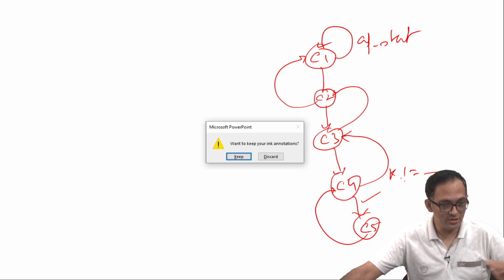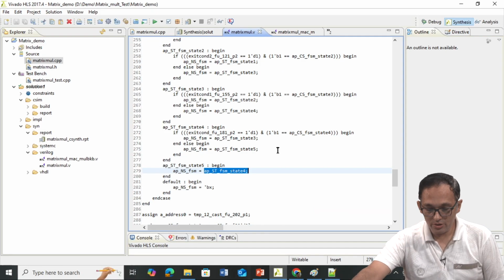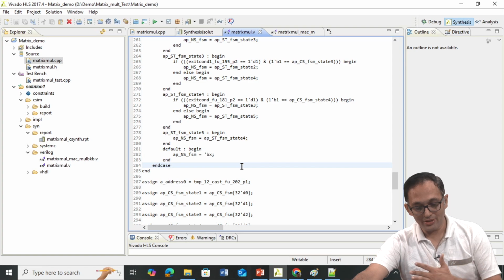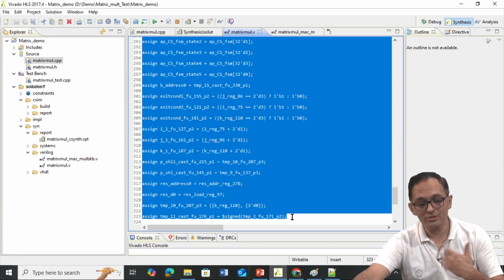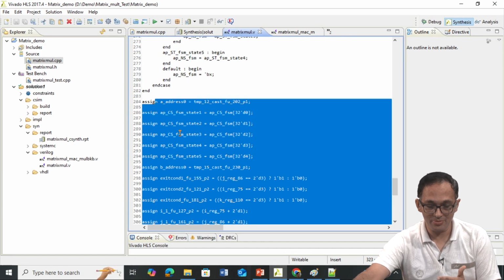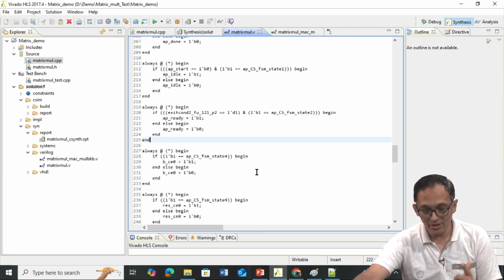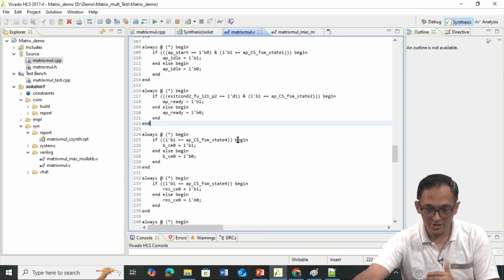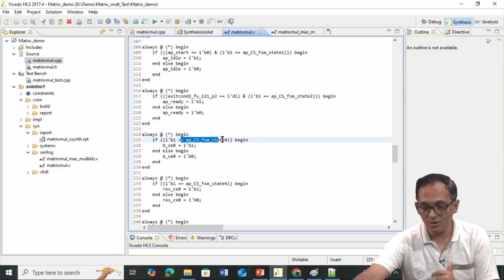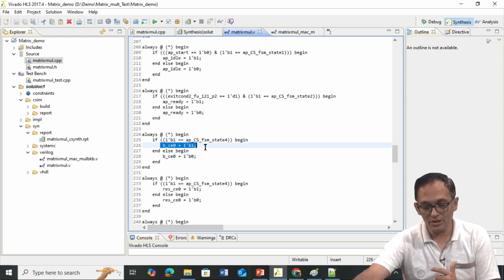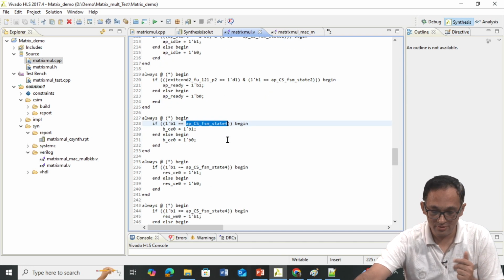Okay. So, we understand exactly what this controller implements in the Verilog. Now, look into the code, what is the data path and all. So, these are the data path operations. Okay. So, these are the combinational operations which are done by assign statements, but exactly which operation is happening in which state is controlled by the control signal that I talked about. Here the control signal is given in a nice way. It is basically saying that if it is state 4, you make your C equal to 1. So, this is the control signal. The control signal is controlled by the control state name itself, right.